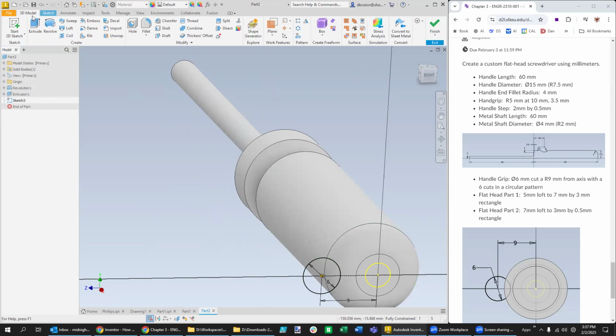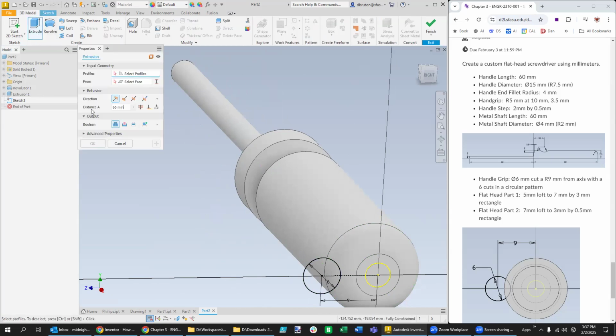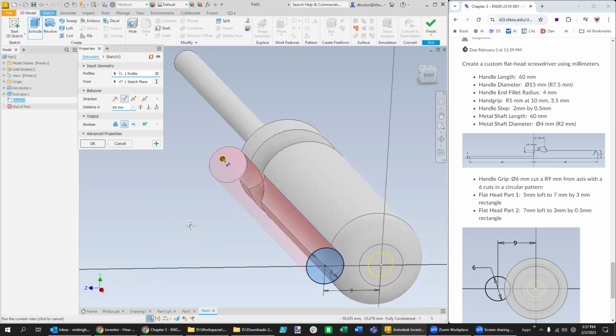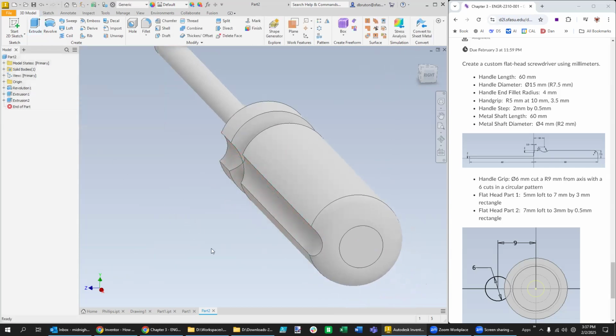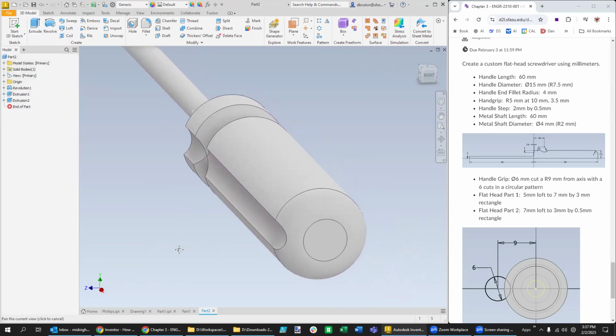So let's begin our cut. So we select the second option to cut. I'm going to use this shape right here, pretty much through everything. It looks like it did the right thing by going through the part that we needed to. And then we need to repeat this as a circular pattern, rather. And so we go up to circular pattern for 3-dimensional shapes.